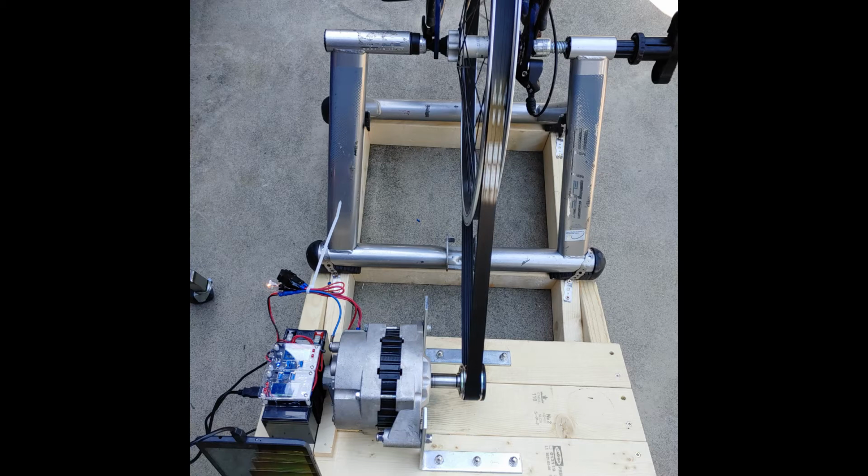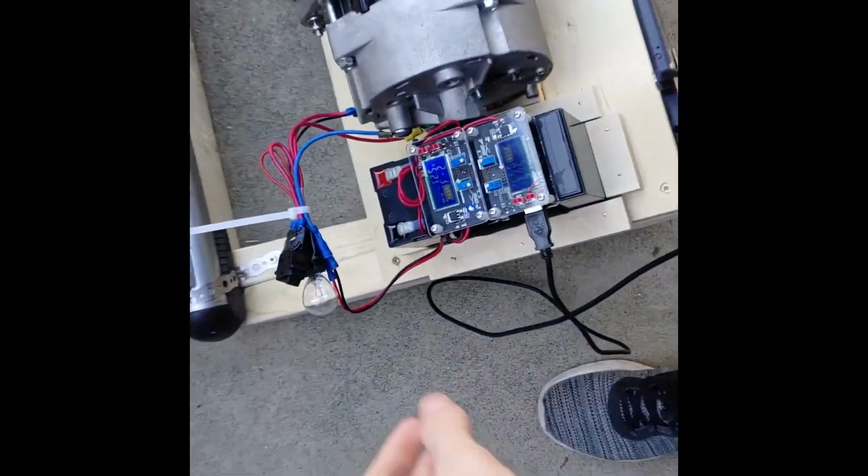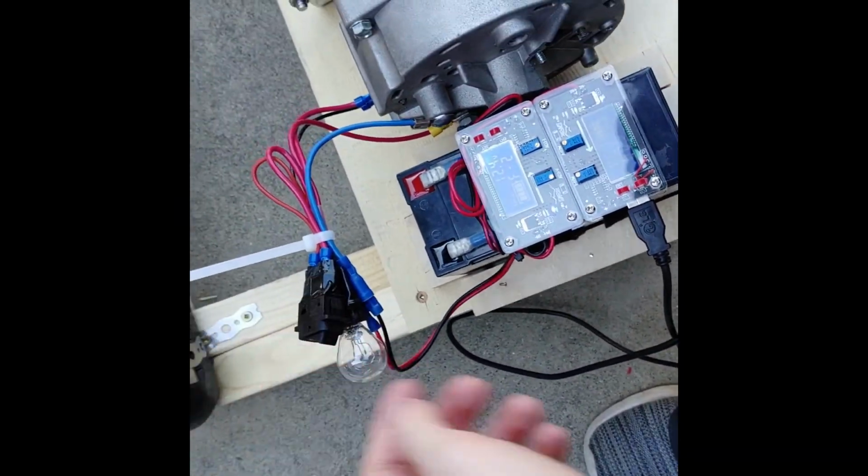The alternator needs to receive 12 volts while spinning at a high RPM to be excited. Those 12 volts were delivered to the alternator by connecting a battery to the terminal on the side of the alternator with a switch. Once the alternator is excited, it becomes much harder to spin because the magnets are on. Here's a video of my system working, and when I flip the switch, you can actually audibly hear the alternator turn on.